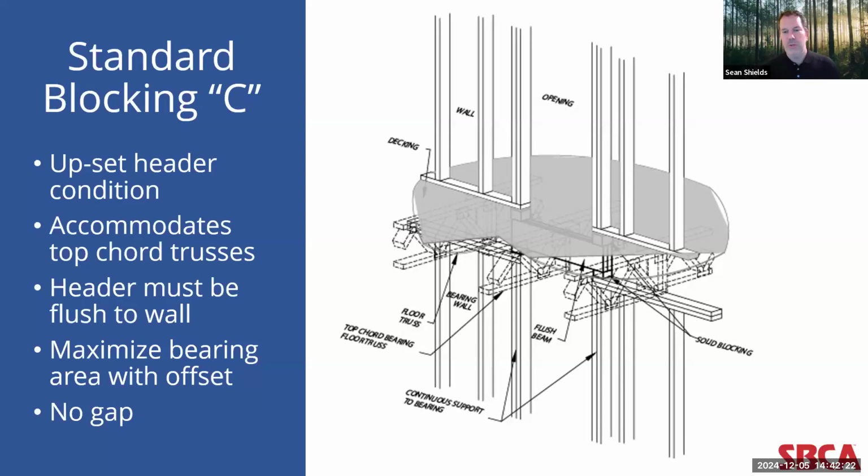Potentially another way to do this is with 2 2x6s, sandwiching a layer of OSB. You can typically get to the desired thickness that way. I just want to note too, another way to do this elegantly is to make that header out of a 4x2 parallel cord truss. Well, it could be a 4x2 or a 6x2, depending on the thickness of that bearing wall. But again, because with the floor truss, the wood members are oriented in the same direction as the top and bottom sill and top plate of the wall, it's very easy to match that thickness and make that header flush.